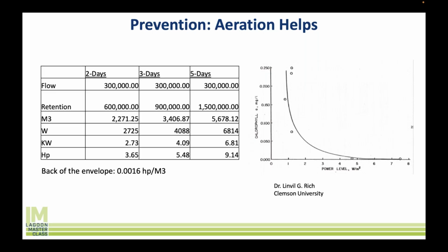This is one of the reasons why, if you do have an aerated lagoon and you have air in your primary cell, that's where most of the time the aeration is the most concentrated, in your first cell, and it tends to taper off as you get through the system. This is one of the reasons why algae doesn't grow in there as much. It's because you're getting this turbidity, all the mechanisms we talked about. You're stripping out the carbon dioxide, right?